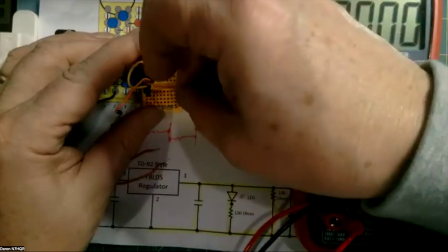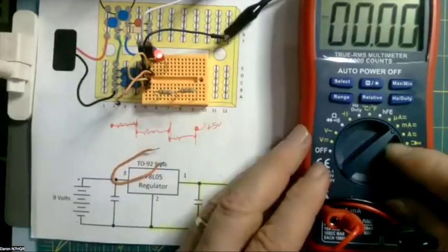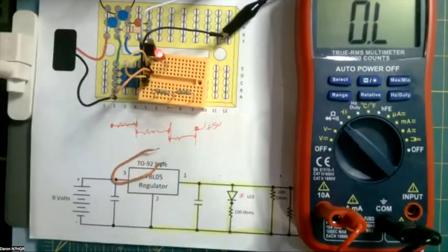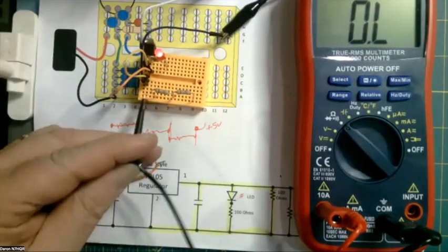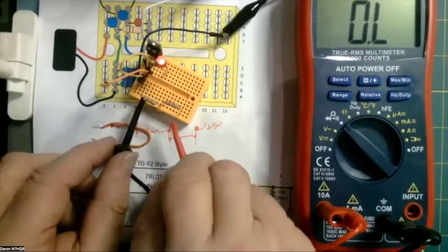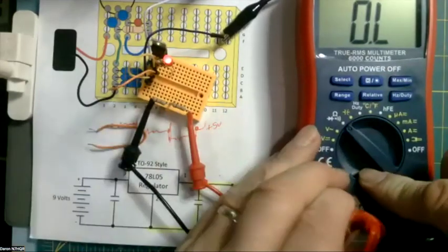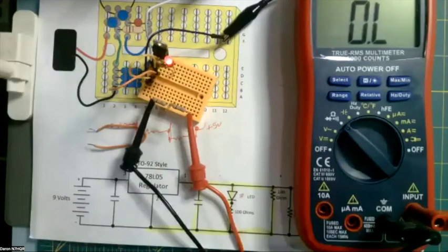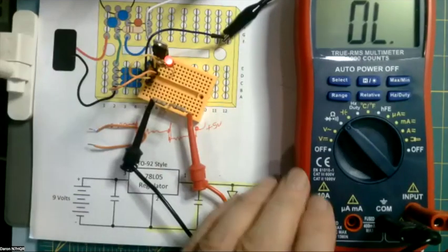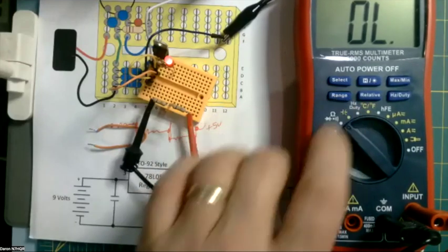Darren is taking two 470,000 ohm resistors and putting them in series, which is close to a million ohms. And he's going to put 5 volts across them. Excuse me, the battery connector. And where does it get its 5 volts from? The regulator. Yeah, the regulator we got on there. Oh, okay.